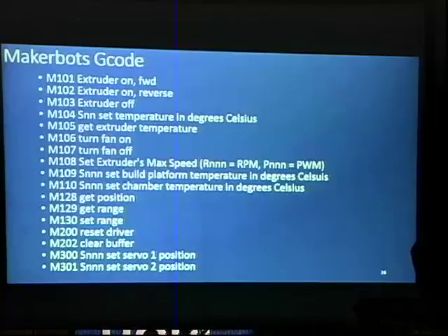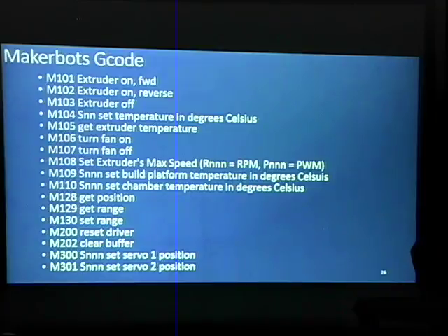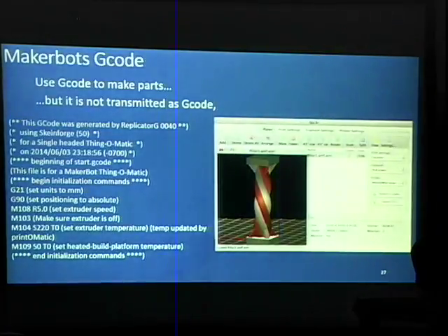There's also a MakerBot-specific M code, and I forget the exact number, I want to say M316 or something like that, that will play a song. Which, you know, I don't think the Mazak machine is going to have the ability to play a song. It's a different use. So if you were to export it before it does that compile step, it looks very similar.